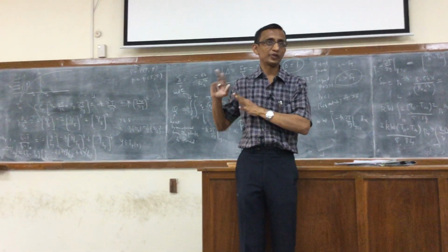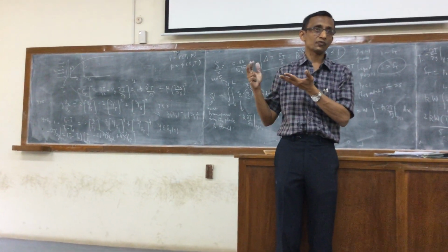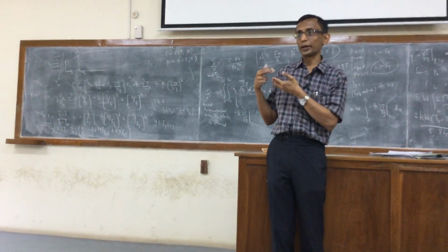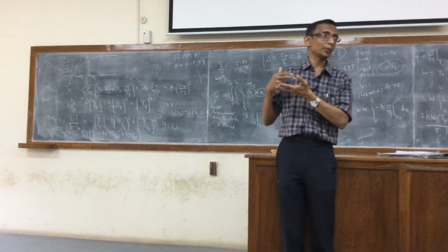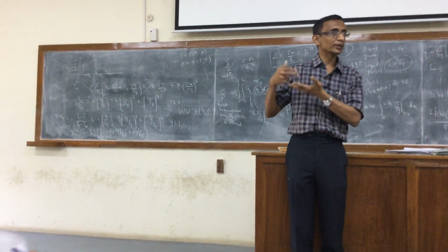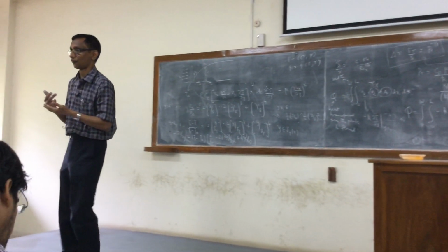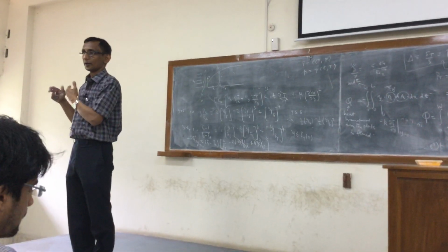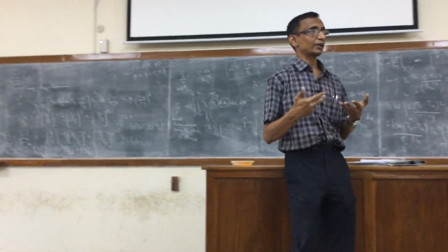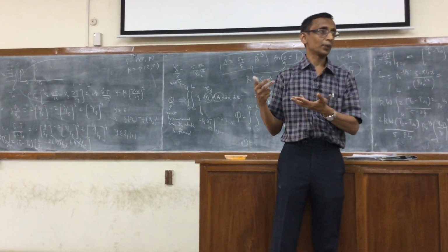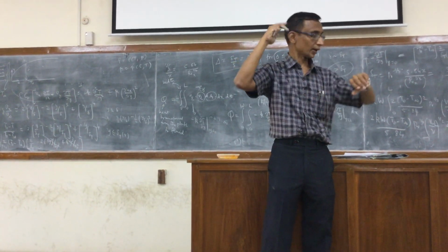It's finally an approximate fit to the actual temperature and velocity profile, as we saw in the case of the hydrodynamic formula. Also, effectively the Vx expression is coming from a fit to f prime of eta, which is obtained by solving the third order differential equation, actually a non-linear equation for f, right? And then fitting the given profile of f or f prime, we get Vx, and Vy can also be obtained similarly, right? There's a calculation in the assignment that is given, which we take up next week. Are there any questions?